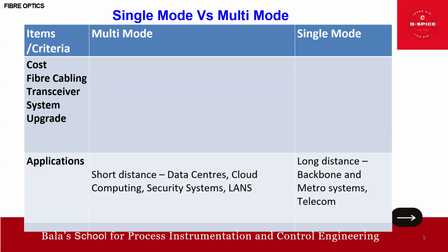Right. Because of the many advantages of single mode fiber, many people might think that single mode is more expensive than multi-mode. However, the opposite is true. Is it strange, right? Yes. The reason is that single mode fiber is more efficient to manufacture, saving an average of 20 to 30% compared to multi-mode fiber. There's no doubt. But if we consider the more expensive OM3, 4, 5 fiber, single mode can save about 50% or even more.